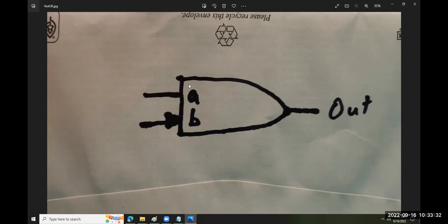So what I have to do is build the HDL to create this. And I already have my logic statement. Remember, we already performed this. We did the truth table, we did the canonical, then we took the simplest case of the reverse canonical because there was only one output that was false, right? There was only one output that was false. And we identified that when one of these was true and the other one was false, the output was false. There was a single case. Does anybody want to see that again?